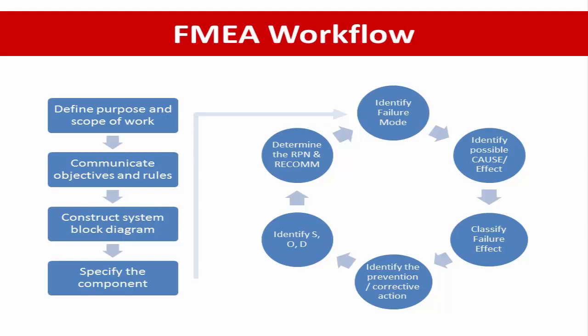Identify the corrective action, preventive measure, or existing safeguard. Then, we determine the severity, occurrence, and detection. And then determine the risk priority number, or RPN. And the last one, determine the recommendation if you have.